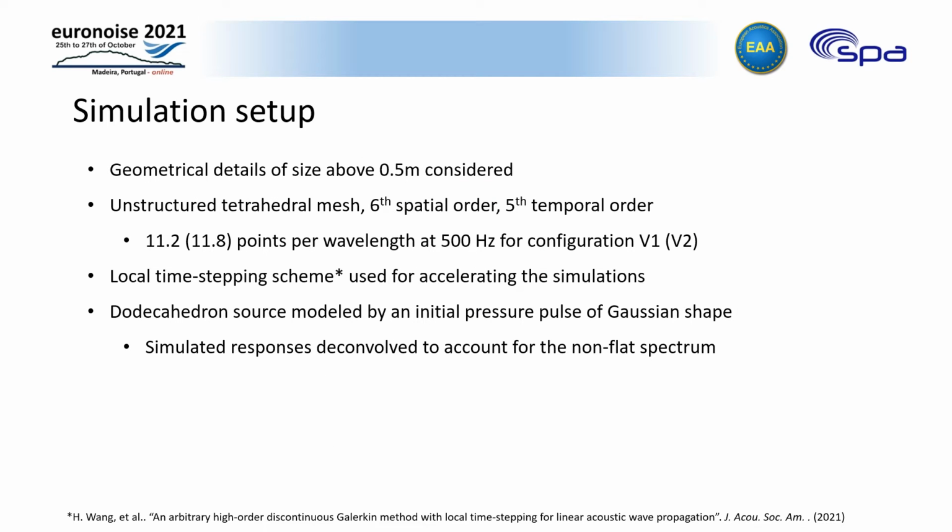Here is the simulation setup. Due to the considered low frequency range, only objects that have a dimension larger than half a meter are considered. It indicates that all the thickness of the tables, gypsum boards, and foams are neglected, which will be modeled as fictitious 2D floating surface in the geometry model.